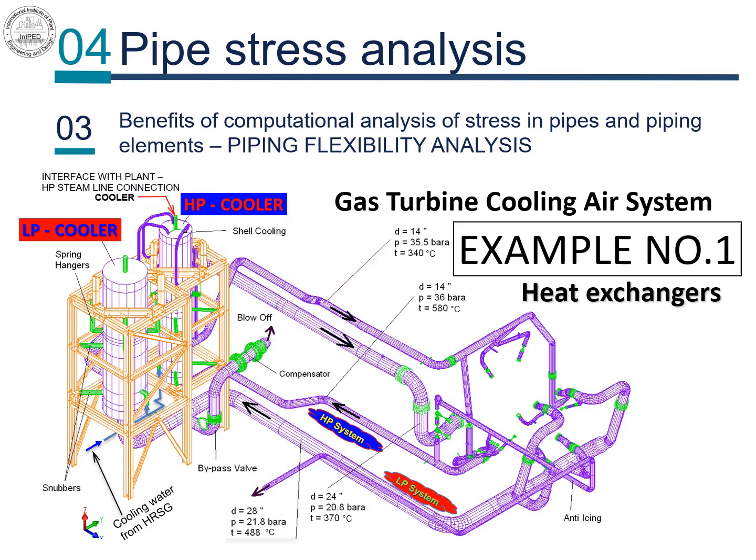The cooled air flowing out of the once-through coolers will hence be used to cool down the blades of the turbine, and it is therefore re-injected to the turbine. As the cooling of the blades on the turbine is very crucial, a too cold gas can definitely damage them, and a too hot gas can fail to cool them sufficiently. The outlet temperature of the air from the once-through cooler is very important, and is the variable that will need to be controlled.